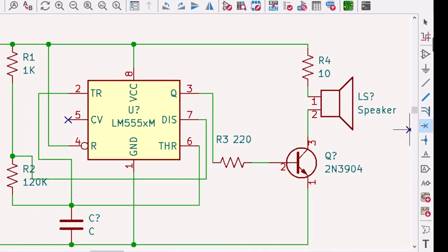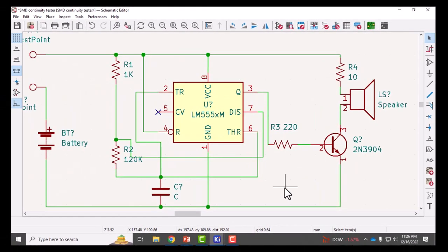there on pin 5. And what that does, I don't think it's a good idea to leave floating pins, which means pins not connected on an IC, but since our original schematic had that and I breadboarded it, it worked fine. Normally you would tie unused pins to ground so that they know that there's a certain reference voltage on those pins. Otherwise sometimes you get weird issues happening. But for now, I'm going to leave that as a no connection to demonstrate how you would use a no connection flag.